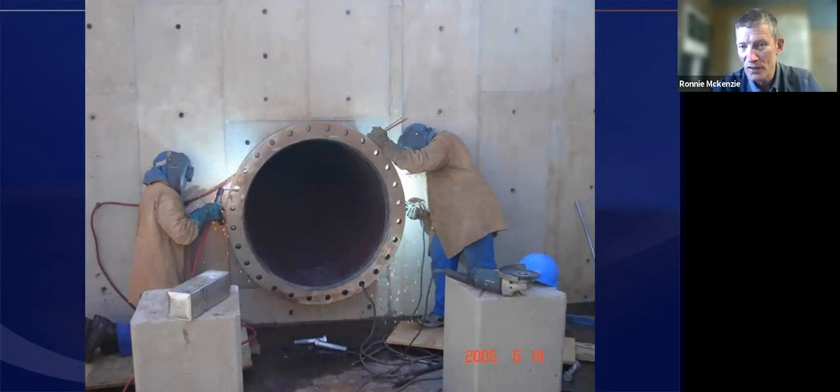We learned lots from the Kailicha one, so we knew what we were doing by this time. You need those flange plates. You also need to pressure test your installation before you put it in. That's another pointer. If you're going to do a big installation like this, do a test water cut to make sure that you can cut the water off to the installation. That's a very important thing. Don't believe what anyone tells you about the upstream valve being great and it was serviced 40 years ago and it seals completely, because it's a lot of rubbish most of the time.